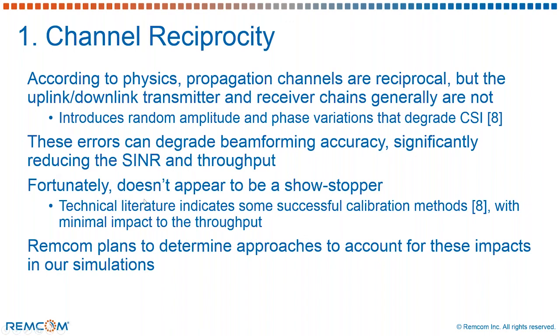When this happens, multiple UEs can be transmitting the same pilot sequence as another UE in a neighboring cell. And as shown in the diagram below, when one UE transmits a pilot and another one sends an interfering pilot, this contamination can cause the pilot to degrade the channel state information from the base station, and this can seriously affect the beamforming.